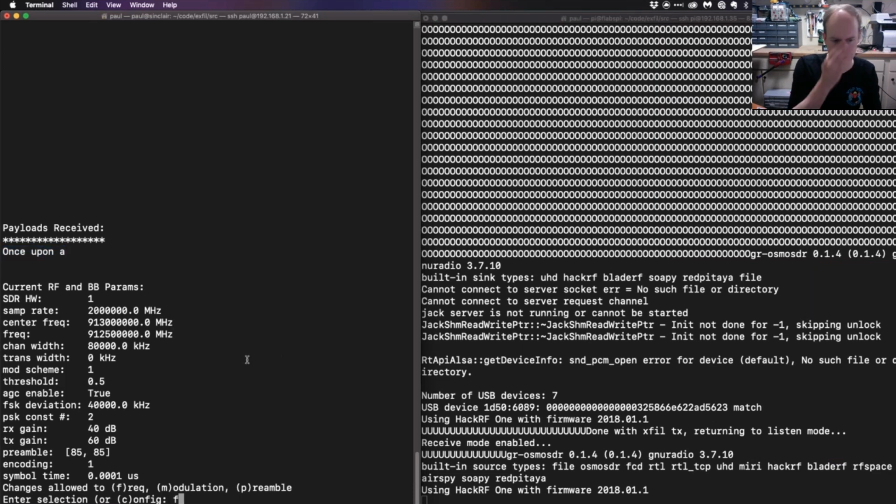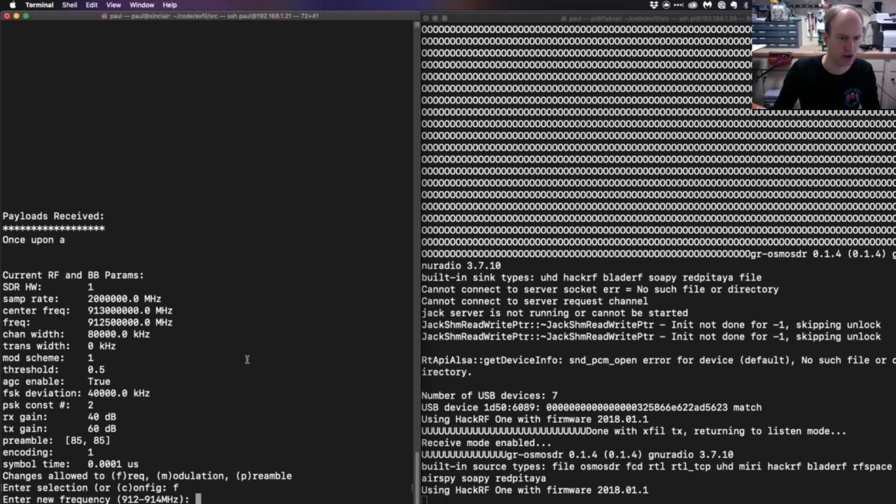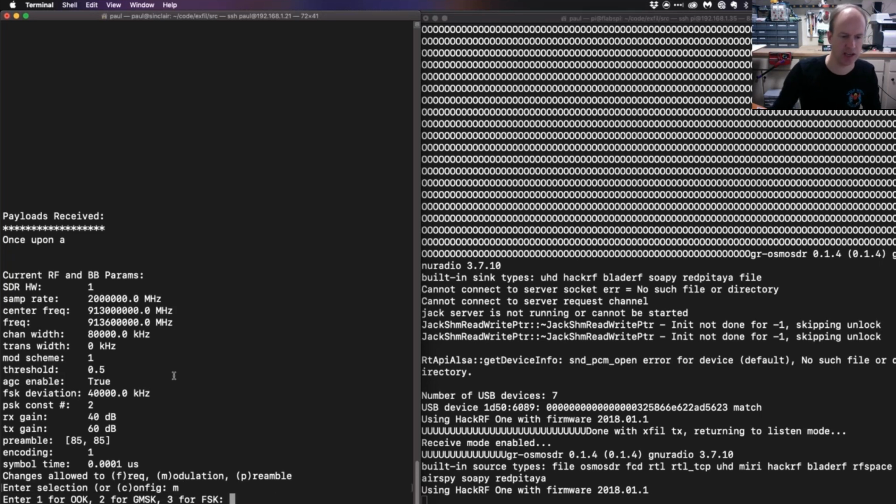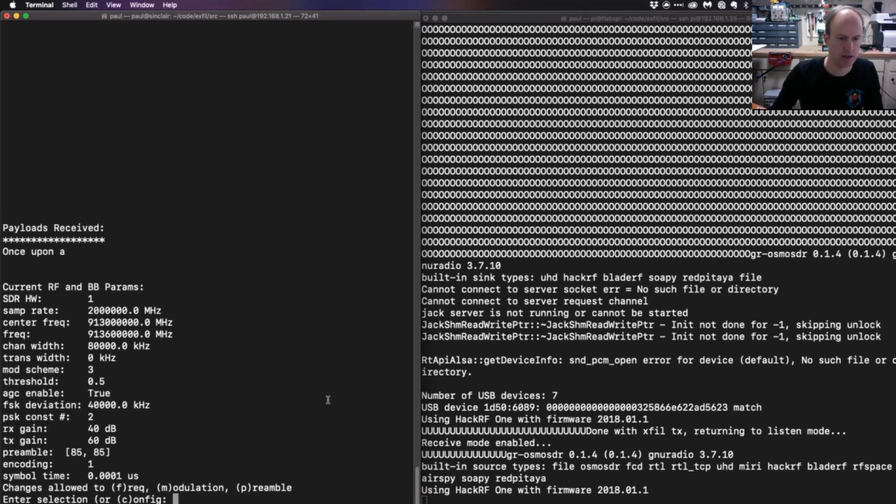And so if I start off at 912.5 megahertz, let me just change it to 913.6. And you can see how that changes up here. And so now this is the frequency I'm dealing with. And let's get crazy and change the modulation scheme. Right now it's 1. And I'm just going to make it FSK instead of OOK. So now I've changed both the frequency and the modulation scheme.